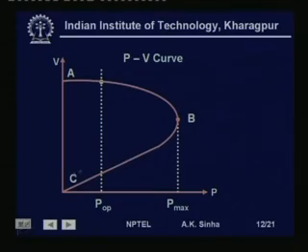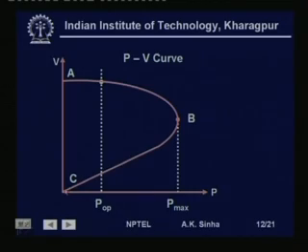That means it will reduce the power again, which will again reduce the voltage, and so it will reduce the current and power. So this will be a runaway situation, and finally the system will go to 0 voltage, there is 0 current, that is the load will be thrown off, that is the load will become 0.